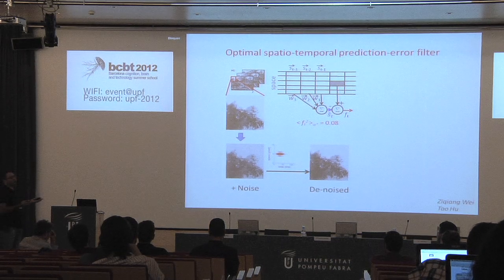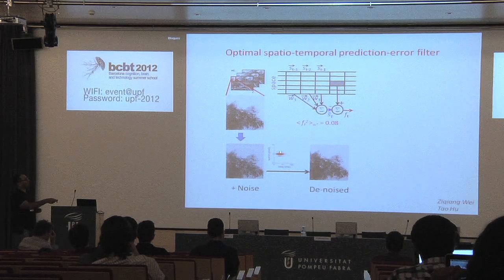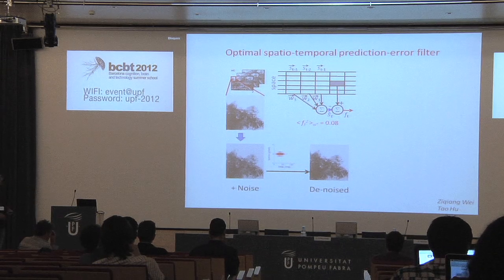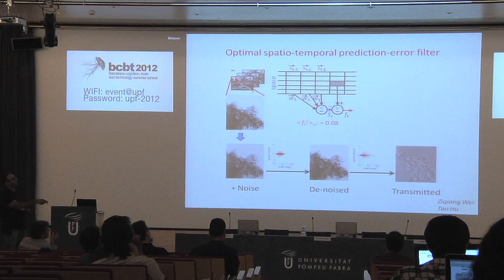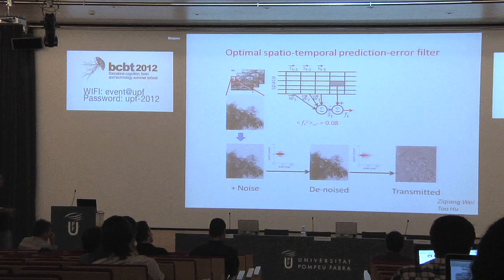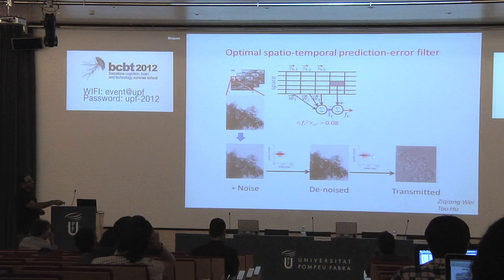I cannot draw you things in three dimensions, so what I will draw is a cross-section of the filter in the time-space plane. And this Gaussian-looking blob is the optimal filter for this movie with the white Gaussian noise. Once that signal got denoised, you can put it through a predictive coding filter, which is also computed through the Wiener framework, minimizing the squared error. And it also has a delta function at zero time, and then a predictive component further back in the past.